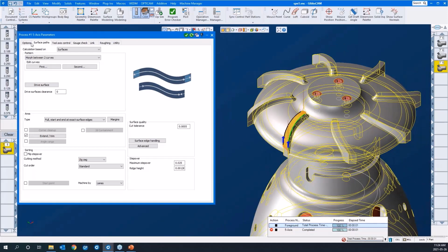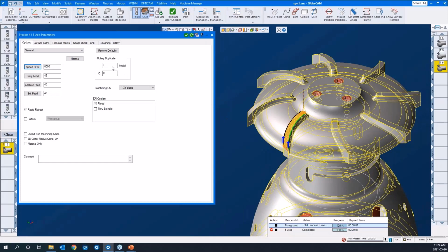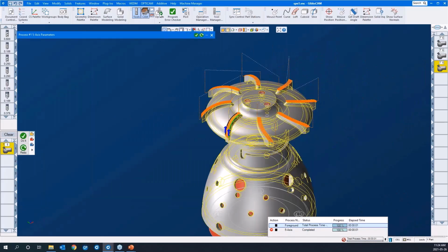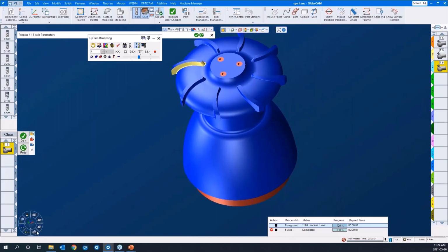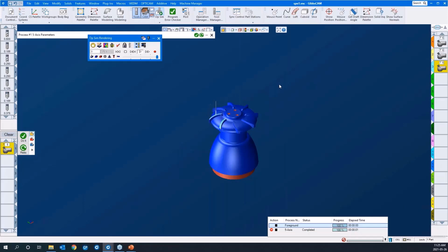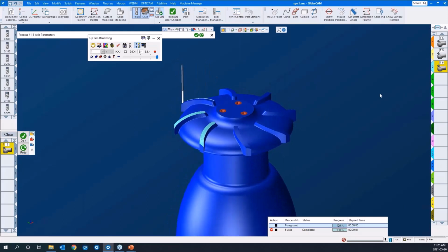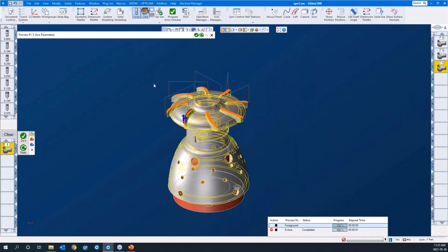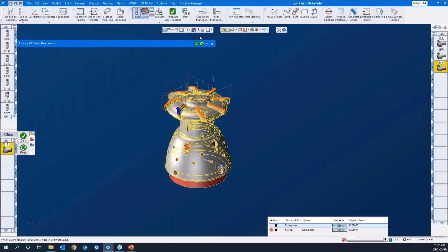One more thing we can do here is I'll go back to the options tab, and we can duplicate this toolpath 7 times over 45 degrees and say redo. Like so. I'll just run the simulation again. And hit play. Away it goes. Of course, I would do that at the end to all of our operations so that the entire part was cut. I'll turn off edges here.